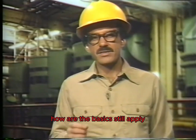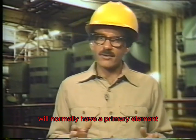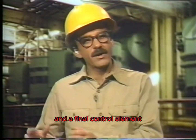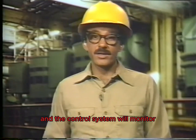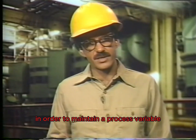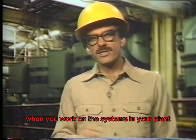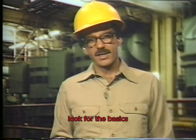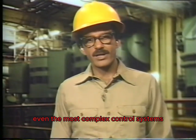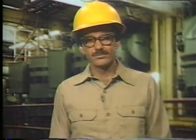However, the basics still apply. Control systems, regardless of how they appear, will normally have a primary element, a measuring element, a controlling element, and a final control element. And the control system will monitor and manipulate variables in order to maintain a process variable at or near set point. When you work on the systems in your plant, look for the basics and use the resources available to you. And you may find that even the most complex control systems will be easier to understand and to work on.